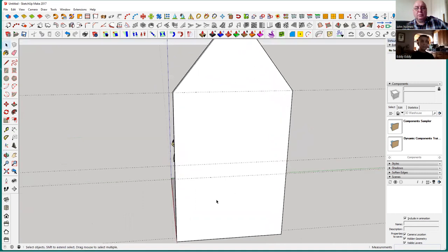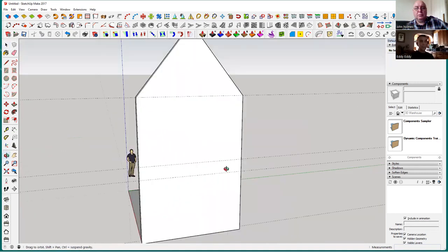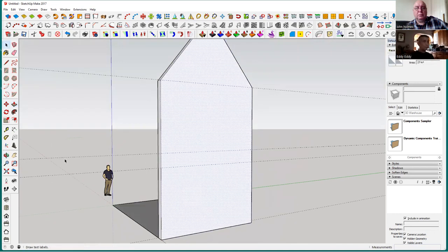Now what I do is, because we're making the frame of the house, this wall wants to be offset by 5 millimetres, so we give ourselves a 5 millimetre frame. So if you highlight it, as it is there, on the left-hand side, we use the offset tool. Click, and it's on the edge there. Click on it, move it in, and this will offset the whole building into the middle. Type in 0.5.